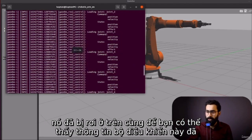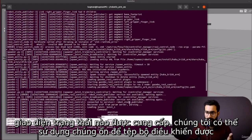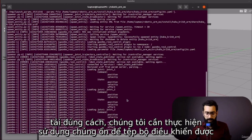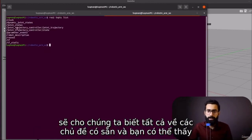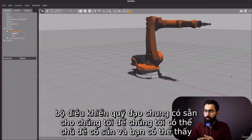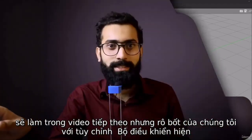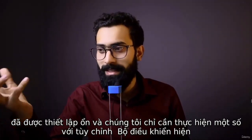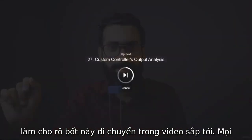You can see this controller information has been provided: for which joint, what command interfaces are provided, what state interfaces are provided. We can utilize them. Okay, so the controller file is loaded properly. We need to perform a final check. ros2 topic list is going to tell us all about the available topics, and you can see the joint trajectory controller is available to us, so we can make this robot move. That is what we are going to do in the next video. But our robot with the custom controller is now set. We just need to write the nodes and make this robot move in the upcoming video.